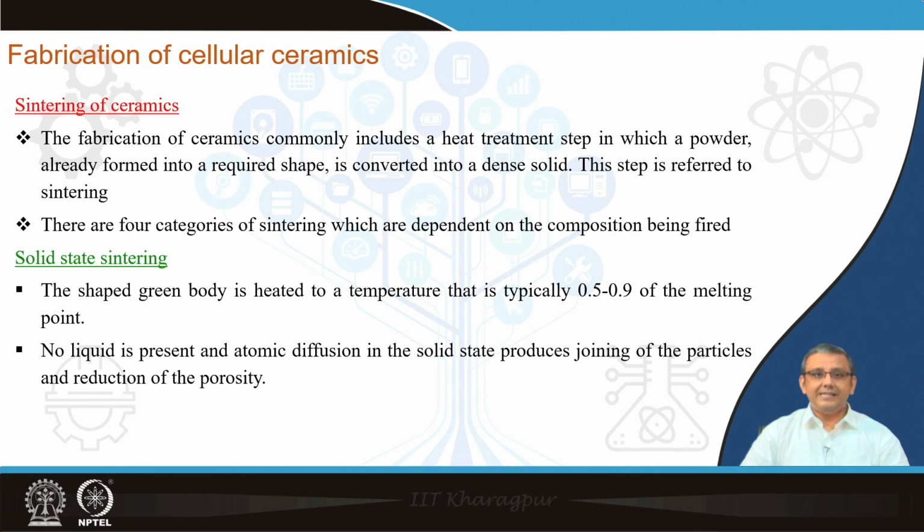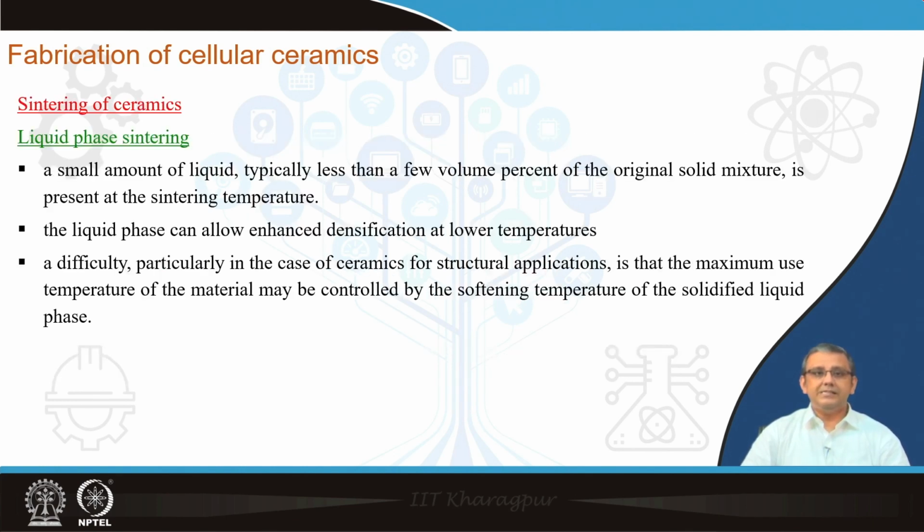Now, in case of solid state sintering, it is called solid state because no liquid is present and the main mechanism of bond formation is atomic diffusion. As I already mentioned, this solid state sintering process is most commonly used for porous ceramic fabrication. There are other variants of the sintering process like liquid phase sintering.